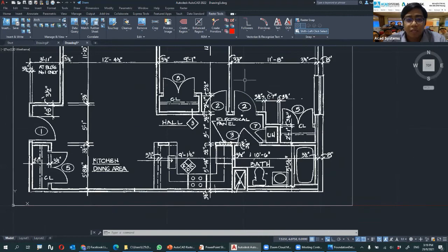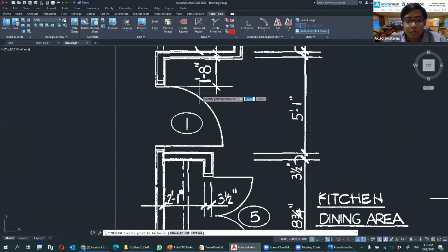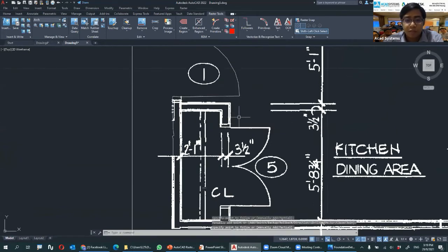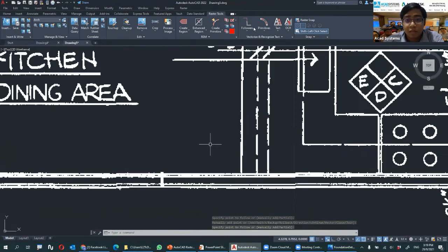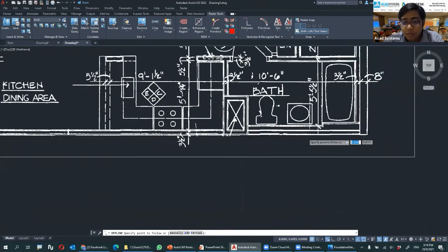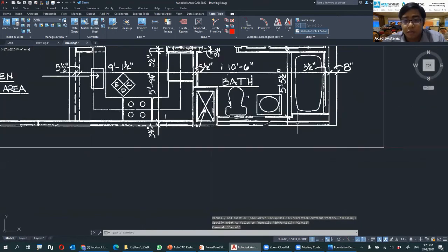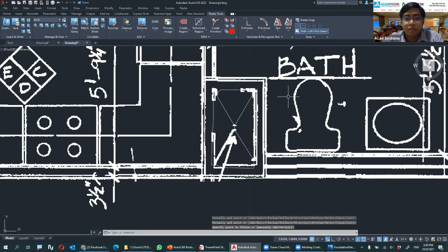And if you want to automatically select everything that has been included, you can also use follows, right? So basically choose one, and it will try to highlight some of this area. Just press enter, and it will convert it automatically. Right? So we have primitive, which I can use one by one, or I can simply use follows and just convert this particular line. So for example, I want to convert this line, so I just click this one, press enter, and it will convert into line.